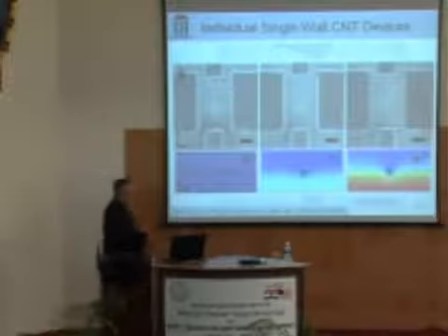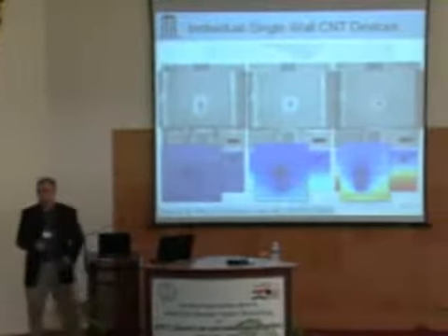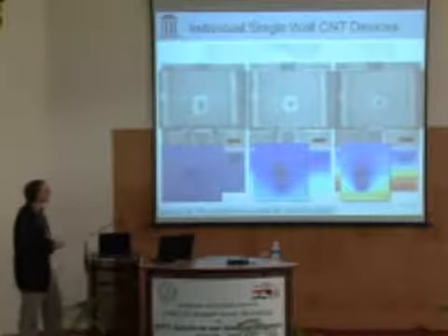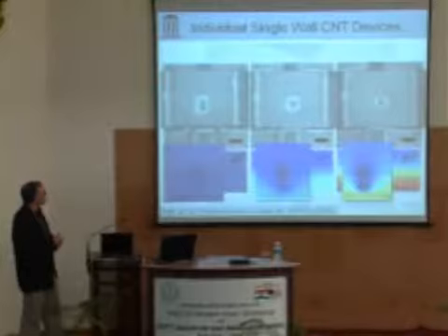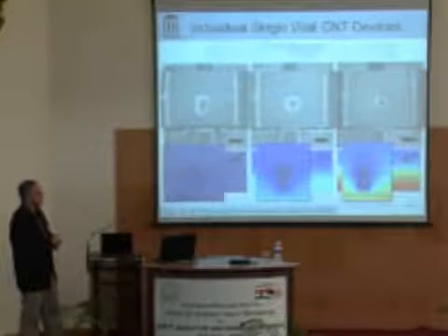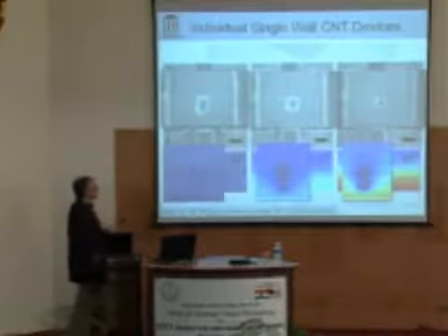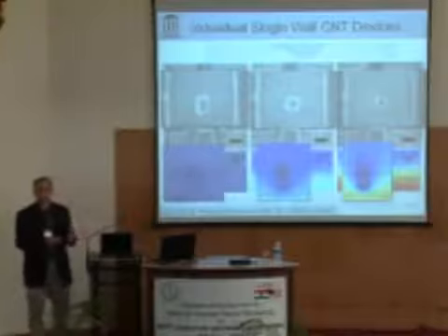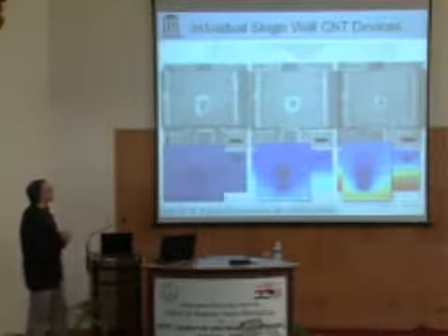We do simulations of the electric fields and the torque on the device in order to calibrate the torques that we're applying. This is just a blow up in the twisting of this. And through our calculations here, we can measure the twisting or the torque on the device to measure the torsional properties, the mechanical properties of an individual single-wall carbon nanotube.